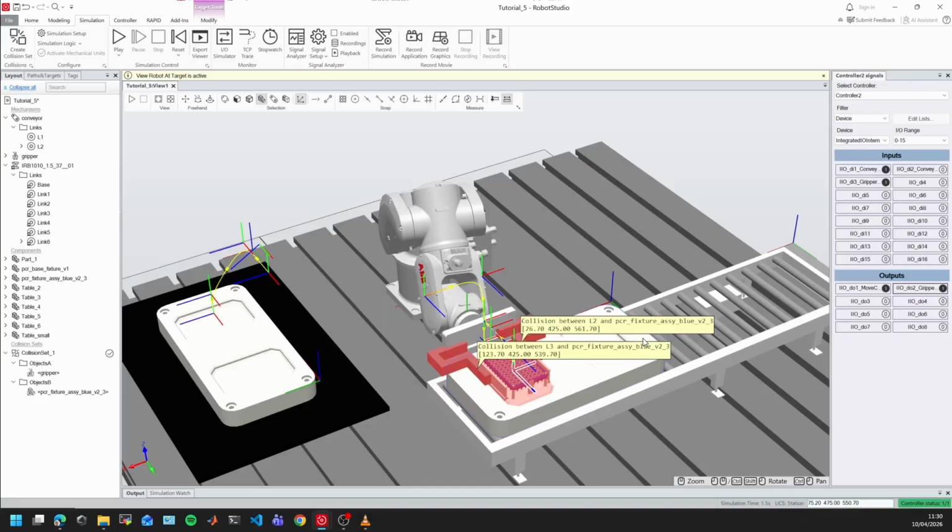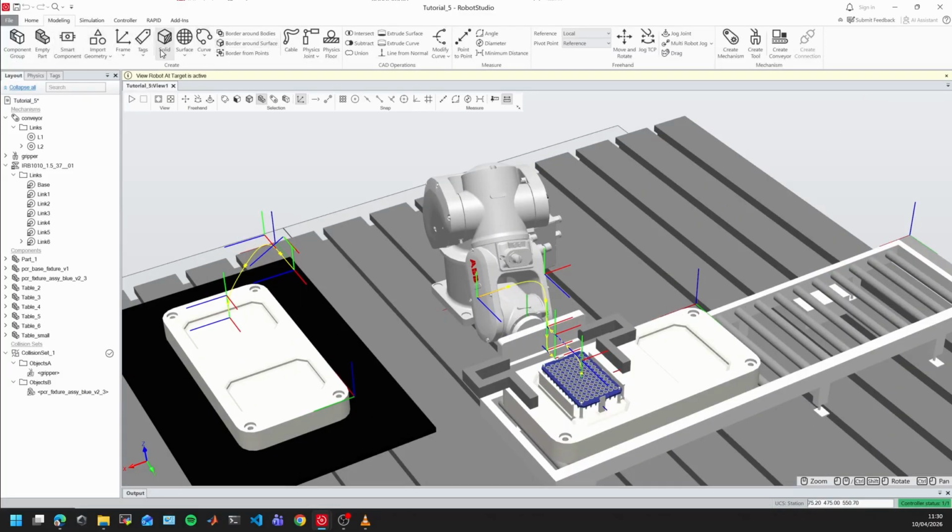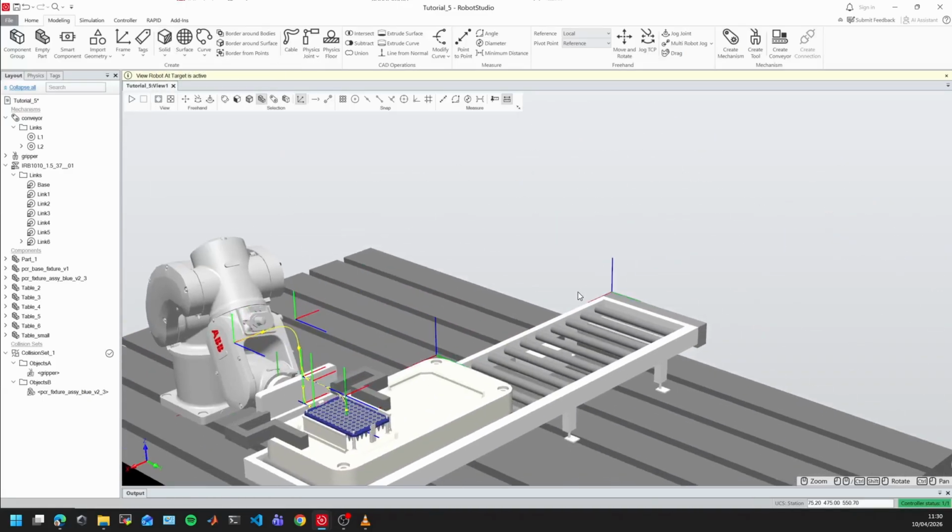But I can use collision to trigger events. Like I was telling you, if I want to make a sensor, like maybe one of these laser curtain sensors, what I can do is model a box. I can put a vertical box in this conveyor, like in here.